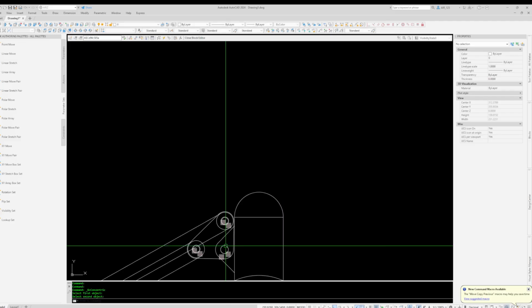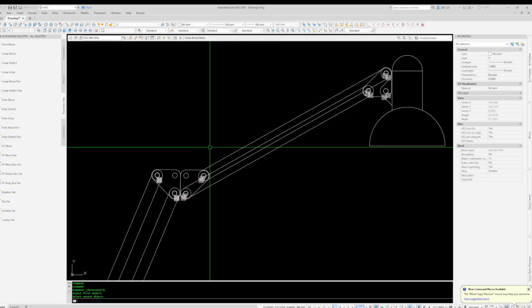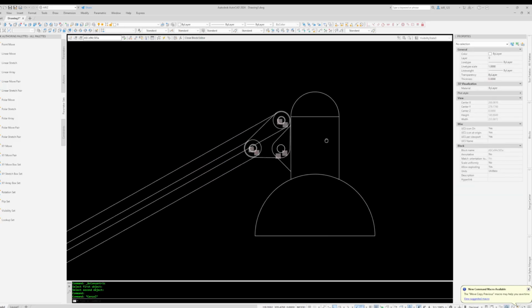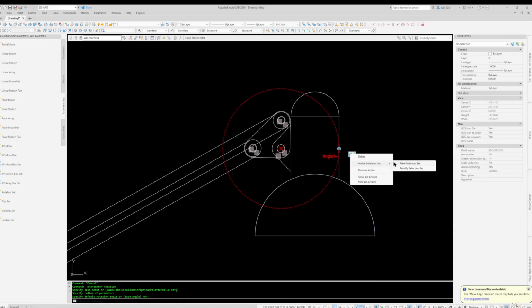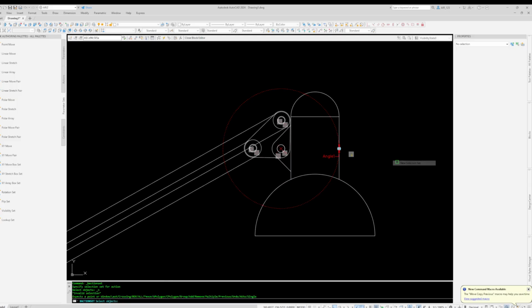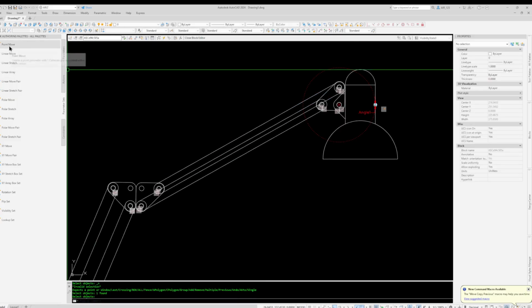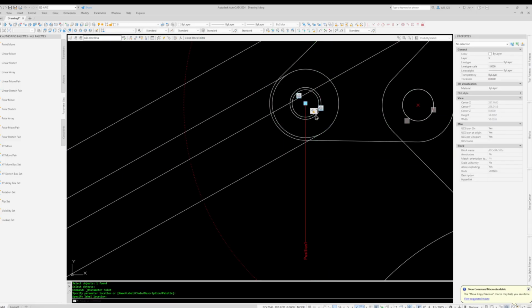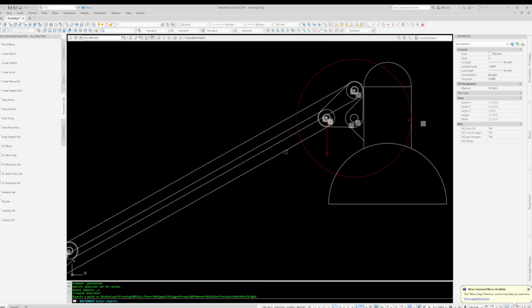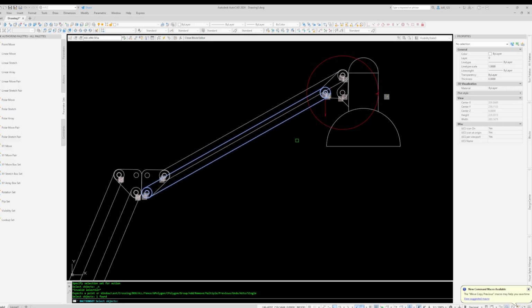So all of them are now concentric. The links and the hinges are concentric to each other, and now we want the lamp itself to rotate at the end of the hinge. So now I'm going to create a rotation parameter, and we're going to create a point move parameter that will basically control how you can move everything together. I'm selecting a link here because you only need to move one part.